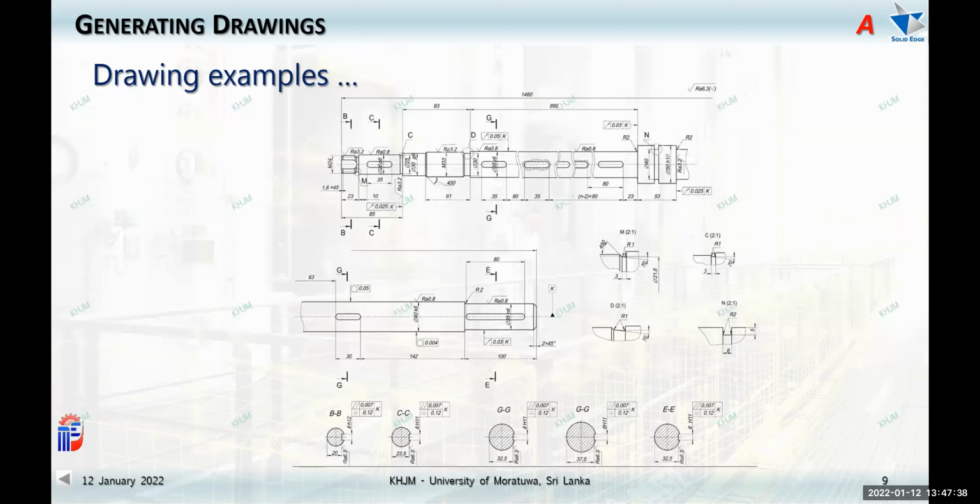Look at this, some more. And even in this shaft, you can see they're all stepped. And look at the bottom line. You have given the details of the cross section of the shaft, not the entire shaft. It's not the sectional end elevation as such, right? So this is the cross sectional view at particular CC. This is called the removed section, right?